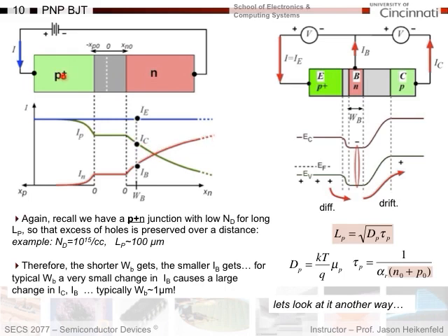If you look at holes diffusing across here, it's dominated by hole current. And the key point is that the closer you are here, the lower the electron current is. Basically, as you go further in, the holes are recombining, which means you need more and more electron current to bring in to recombine with those holes.